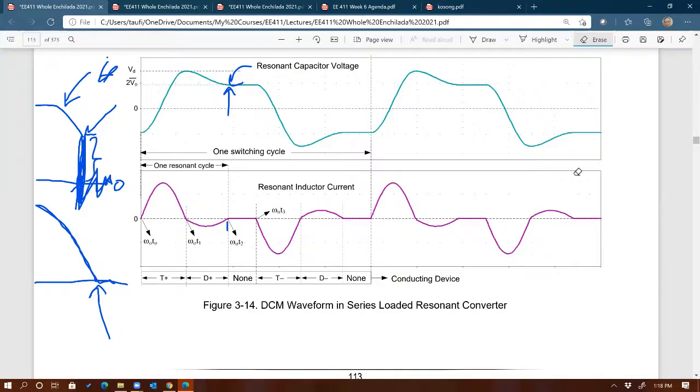So for an application that asks for plus minus 120 kV DC out, definitely you want to use PN junctions, not Schottky's. Imagine how many Schottky's you would put in series. That's going to be expensive and not reliable. So for that kind of application, it is useful to be able to use PN junction, because the voltage rating is high.